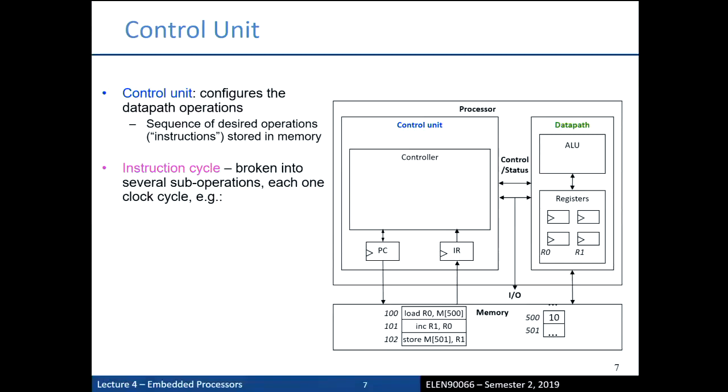But what is an instruction? An instruction is broken into several sub-operations. Well, before you actually run an instruction, you have to go and get it. And the micro here goes and fetches the next instruction into the instruction register, IR.